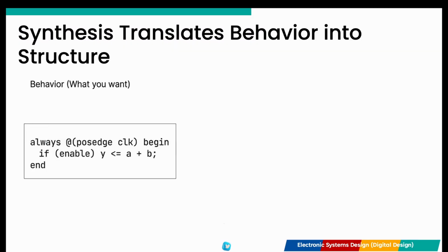During the synthesis phase, the compiler actively optimizes your design to improve both performance and area. It uses automatic techniques like constant folding to simplify static mathematical expressions at compile time, and dead code removal to strip away any logic that will never be activated.